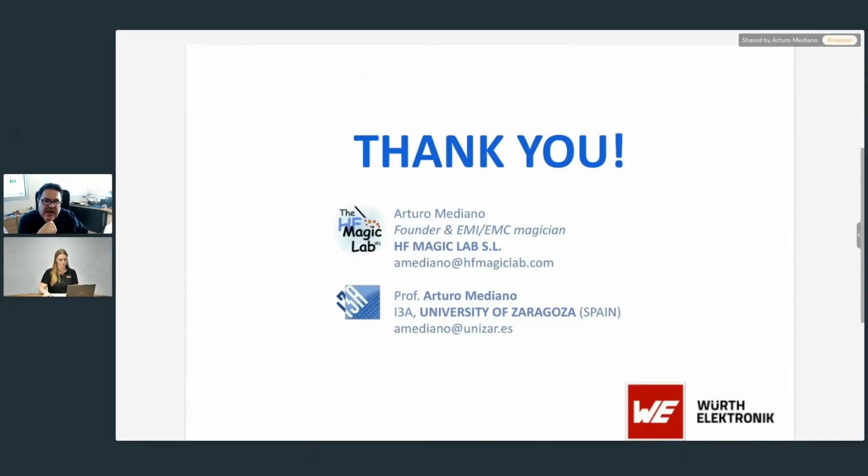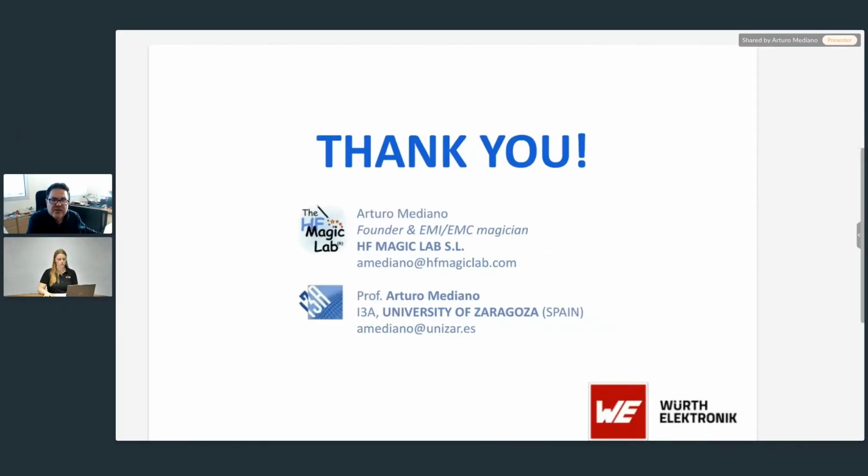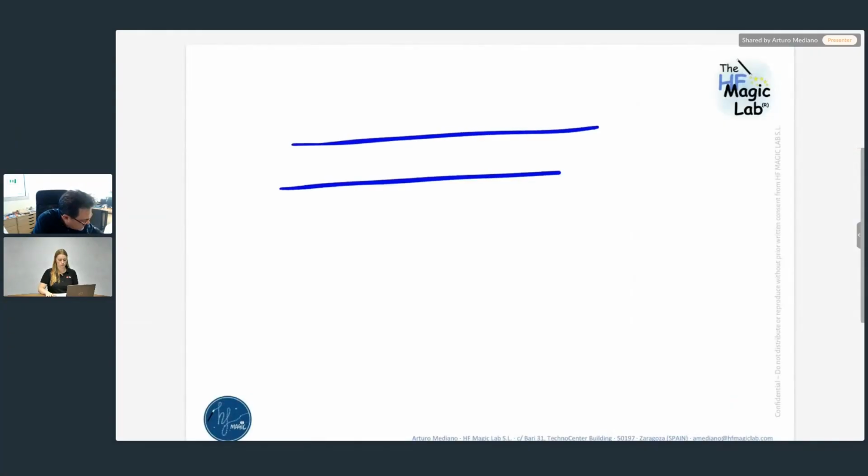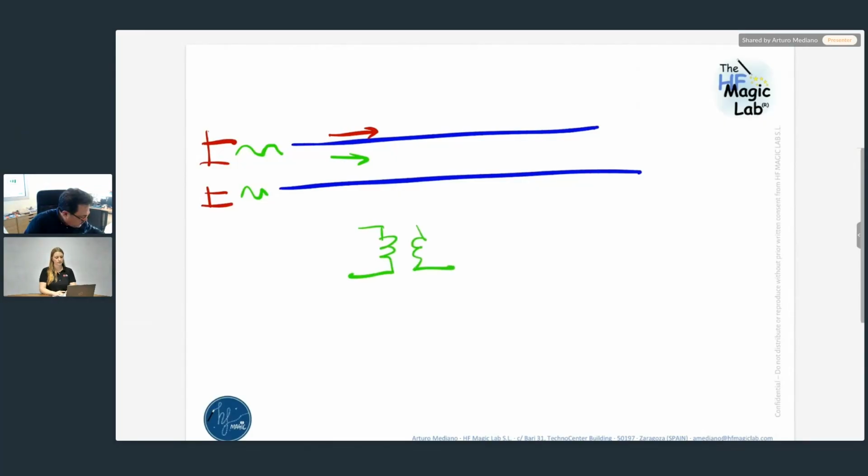Yes. I think I understand the question. Yes, because if you consider that you are sending into wires your signal, and additionally you are sending some kind of DC, the DC and the signal go through the low pass filter. That is, the common mode choke is invisible for DC, so you can send signal. This is the opposite to using a transformer in this situation, where you are not able to pass DC. But if you put the transformer in this direction, this transformer is invisible for DC, for your power.